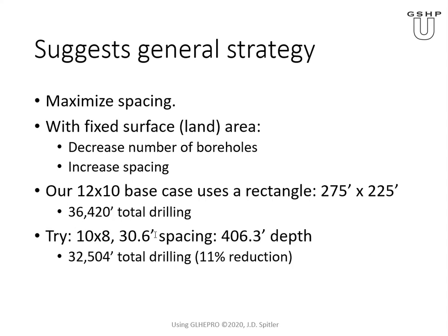But if we went, for example, to something that would fit in the same space, and I just tried one case, a 10 by 8 case, you could go to 30.6 spacing, and you're constrained in one direction or the other. Actually, with a 10 by 8 you could probably have 2 different spacings, although GLHEPRO at present doesn't handle having different spacings in the X and Y directions. So that would give us 32,500 feet of drilling, or an 11% reduction. So that's not bad if you can go to 400 feet.